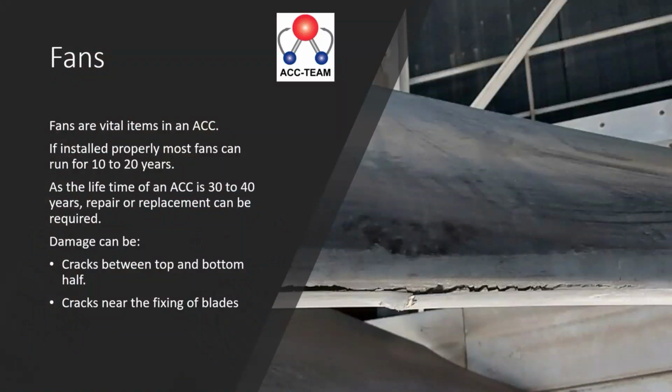We recently encountered an ACC at an incinerator plant. The plant had been in operation for almost 20 years, and by investigations during maintenance, we found various cracks and damages on the blades. We found that this fan had to be replaced, which we did, and we investigated the damage together with the supplier. This was a typical case of damage due to vibrations, conditions, weather impact, etc.